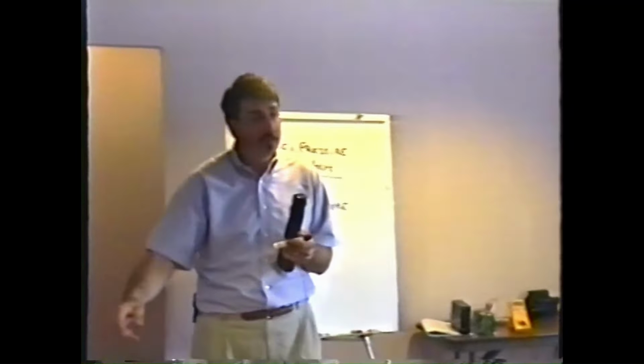You know that if you look at our AC power distribution, it looks like this. And there's a short slot and a longer slot, and then this half round guy, and this is an earth ground. Somewhere in the building, this third round pin is supposed to be connected to like a cold water pipe that's buried in the ground, or perhaps a steel rod that's pounded into the ground somewhere. The earth itself is our 0 volt reference point.